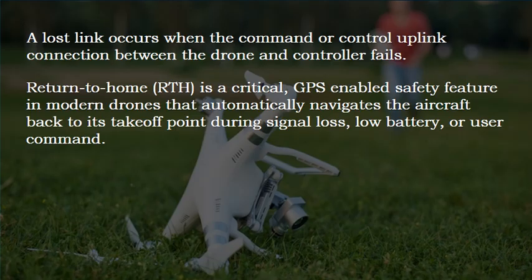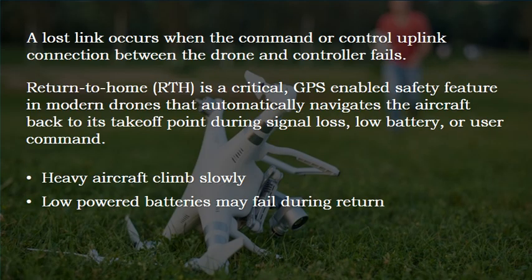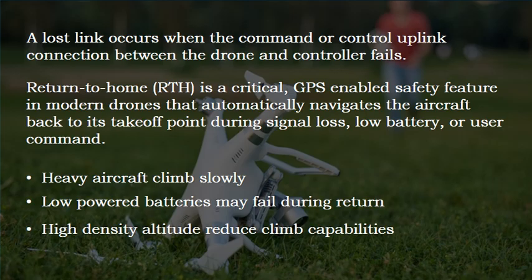Some return to home or lost link considerations include: heavy aircraft slows climb. Low power batteries may fail during return. High density altitude reduces climb capability. And wind may overpower aircraft, preventing it from achieving its return to home objective.